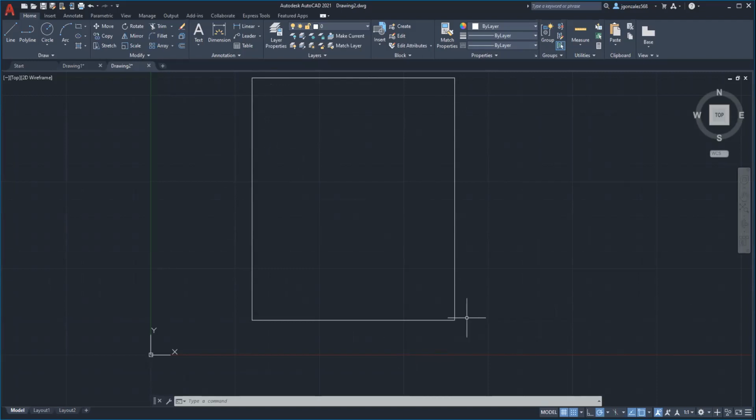All right. Guys, have any questions so far? This is a simple example. Yeah, how are we supposed to? I'm not getting the option to enter the coordinates. You know, hit the pound sign, like hit shift and number 3. It should allow you to start typing a coordinate once you have started the line command. So, okay, line command first. If the point doesn't show up, you can force it by hitting pound and then typing the point. So for each point, make sure you start with the pound sign.